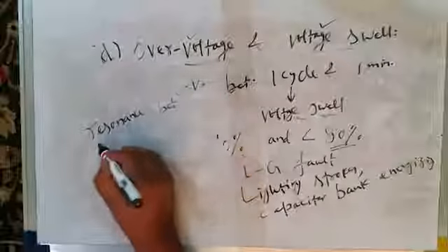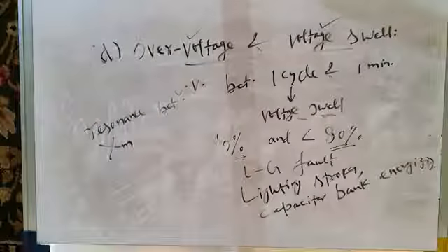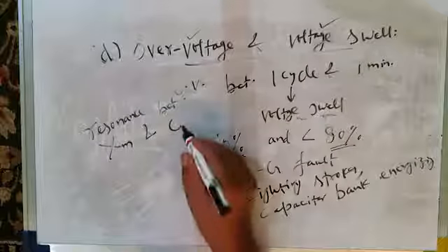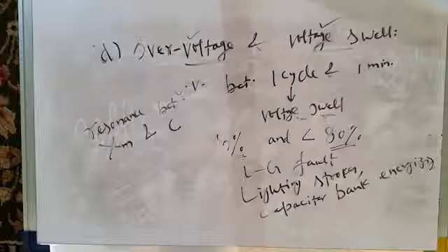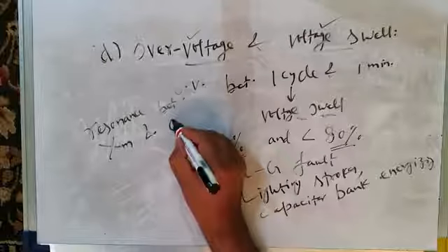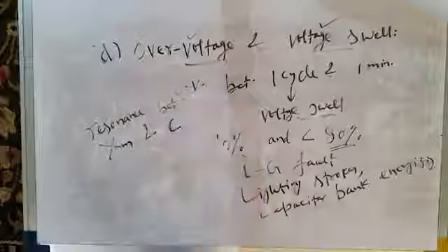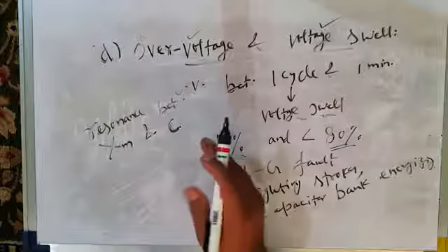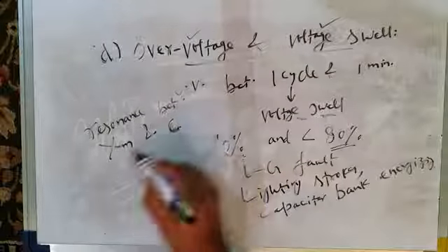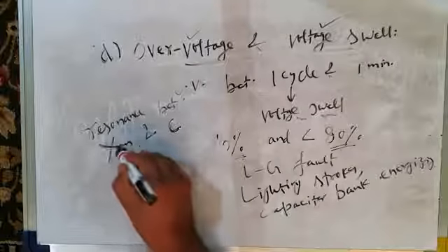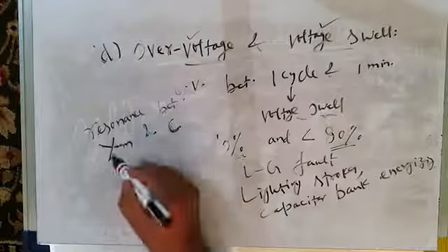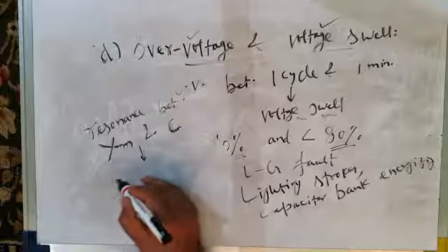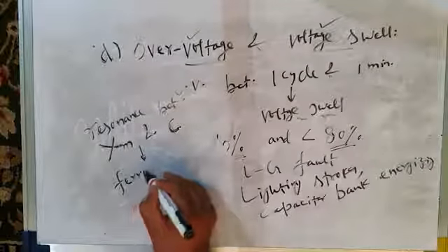between the transformer magnetizing reactance, Xm being the magnetizing reactance of the transformer, and the capacitance of the capacitor bank or the capacitance of the underground cables. Suppose you are using underground cables. Underground cables have strong capacitance. This capacitance of underground cables, or this may be the capacitance of power factor correction capacitors, may fall in resonance with the transformer magnetizing reactance, and that will give rise to a phenomenon called ferro resonance.